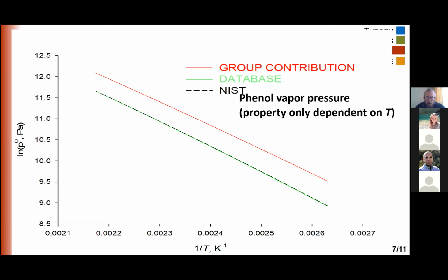However, these group contributions are not the devil, because, for example, in this very example, the heat of vaporization, which is the slope of the line, is kind of well estimated. However, always check the property estimation. If you have the component in the database of the software, use it. Don't estimate the property at random. And when you have to do it, try to check it versus the literature.